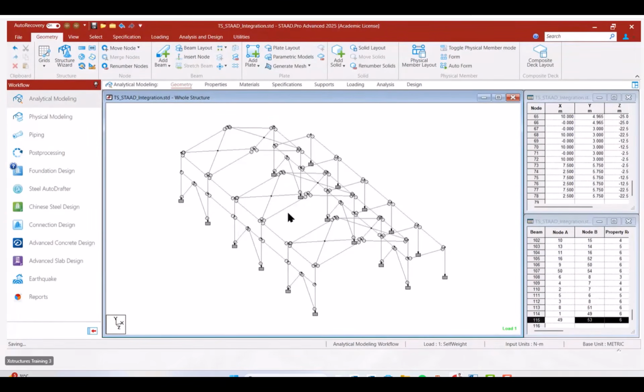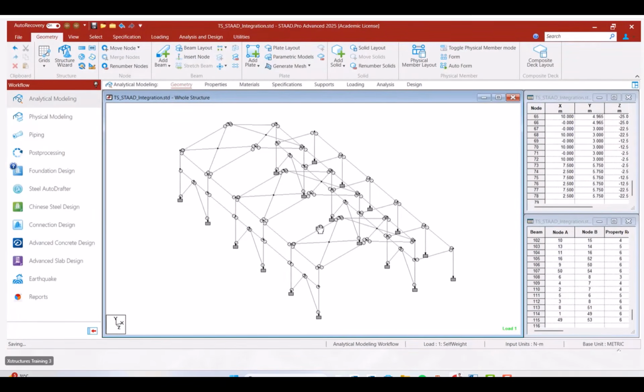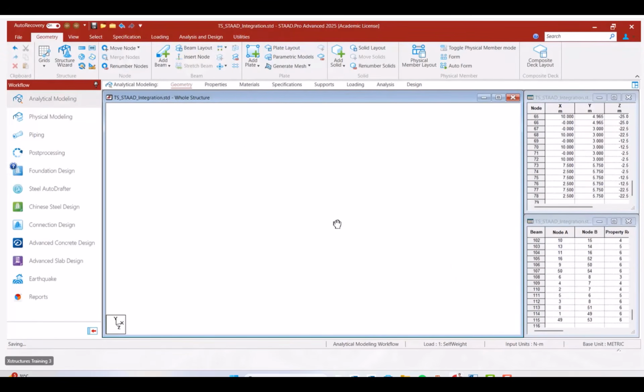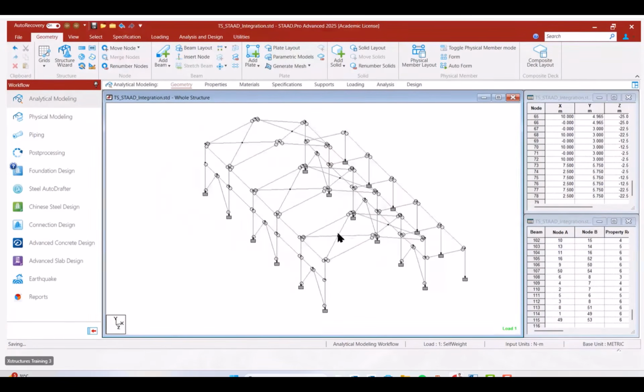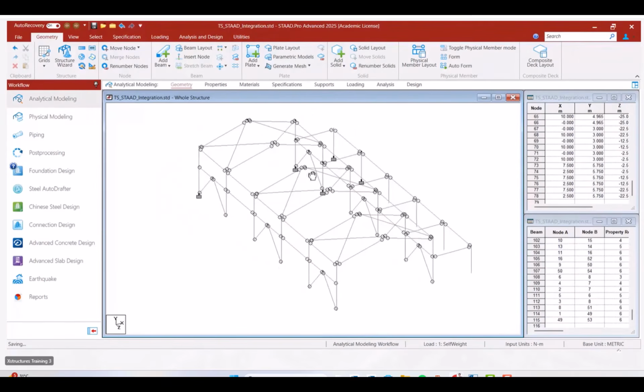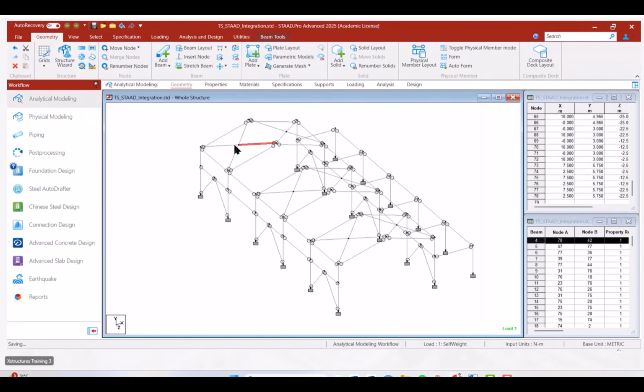So here I just need to modify some of the design or the model itself. Specifically, for example, the tension rods here were actually intersecting at a certain point. So I need to merge them so that later on, when you design the connection, it is oriented correctly.